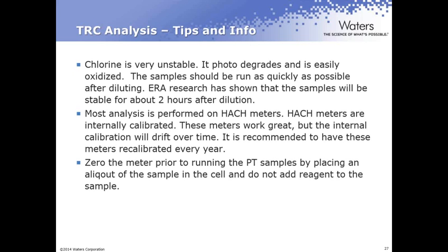And what that means is that exposure to light can degrade the chlorine, it can break down the chlorine, and exposure to air can oxidize or also break down the chlorine. So those samples should be run as quickly as possible after diluting. It's one of the reasons why in your wastewater facilities, you're supposed to run that sample within 15 minutes after your collection.